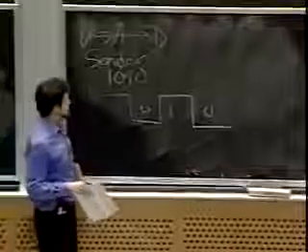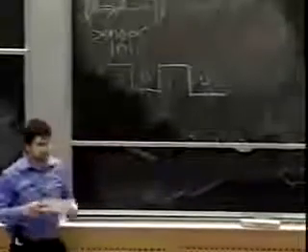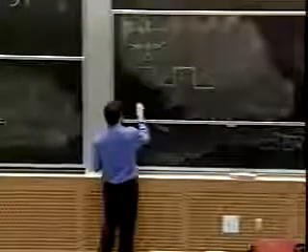You might ask, how do we decide when to push the next bit out onto the wire? Typically we have some clock signal that tells us when we should start sending the next bit on the wire. We might have some protocol that says something like, every time there's a rising edge in the clock signal, we'll start transmitting the next bit. So what does that mean?